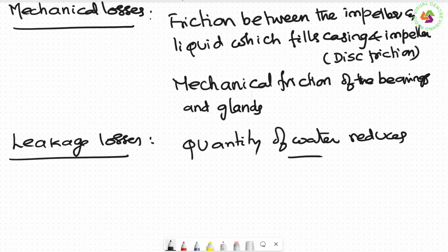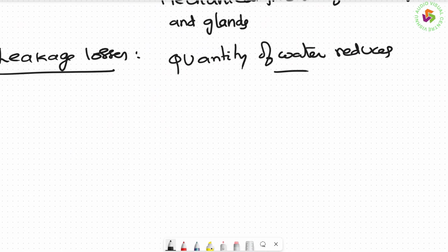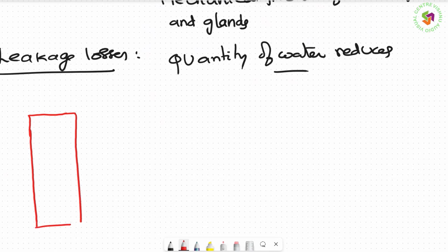So how can I show this diagrammatically? First, where the power is available for us. First one for us is from the shaft, the power is available, because in a centrifugal pump this is what we call the available power. This is shaft horsepower in kilowatts. Shaft horsepower is the available thing, that is what we call P.